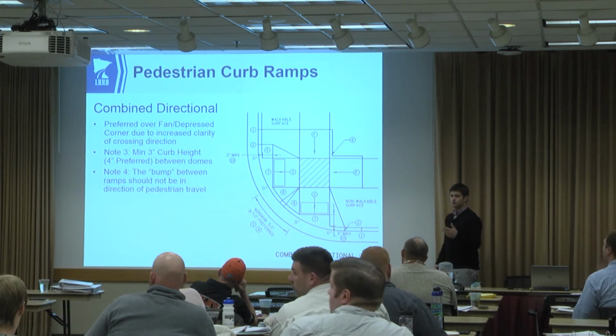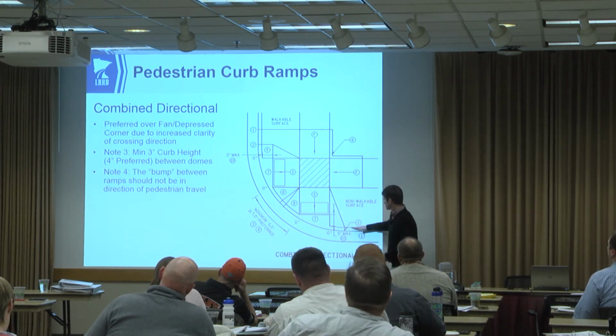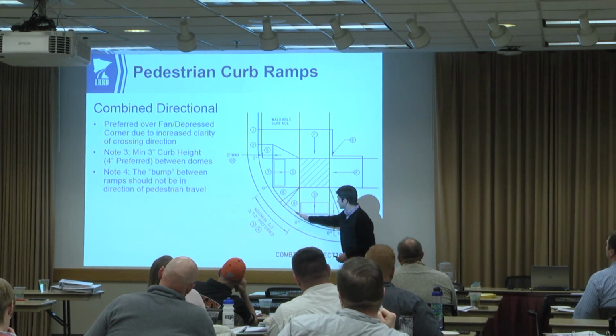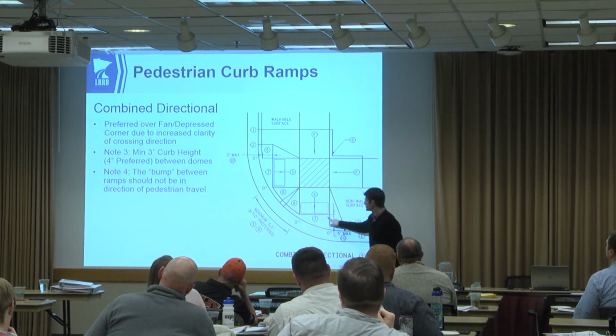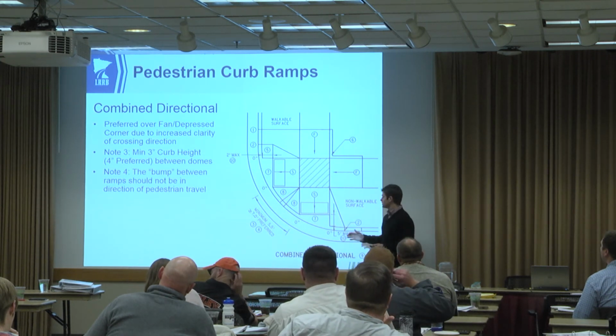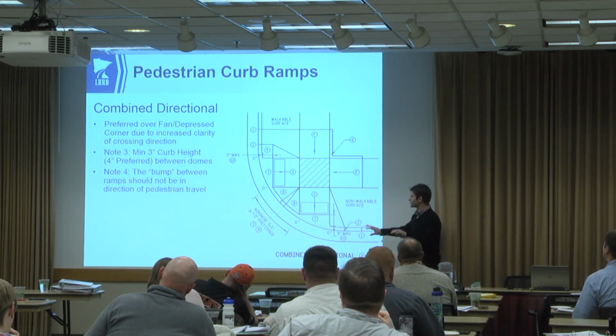Can I ask you a quick question, Brady? Yes. What is considered the back of curb on the long side? It's for an integral, right? Yeah, so you're coming around the radius. Where's the back of it? Do you maintain that through there? Well, remember, this is port integral. Yeah, so where does that 9 inches come from? Maximum 9 inches for the... I'll get there. We're talking about 2 crossings right now. It's easier to think of if we look at 1 crossing just at a time. Compliant, obviously. Yeah, I'll get there about the 9-inch requirement.